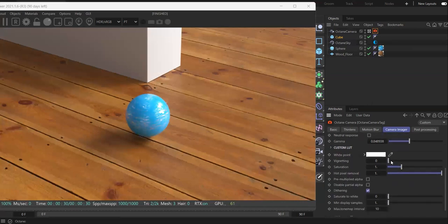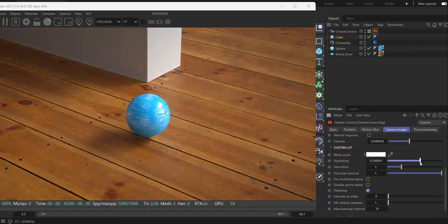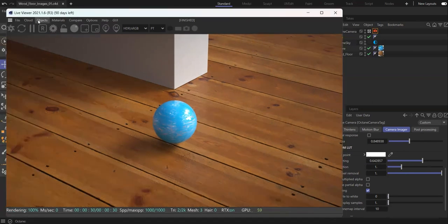And in addition to that, some vignetting, right? To build kind of the central focus in here is interesting. However, you can see the image overall, although I'm trying to draw focus into this area, it's feeling a little bit muted. And so let's add a light in here. It's very rare that I just use an HDR to light my scene and nothing else. Okay. So 90% of the time, if I light my scene with an HDR image, I also incorporate other light sources to either add fill light or add some nice specular somewhere, or a more interesting shadow to my scene.